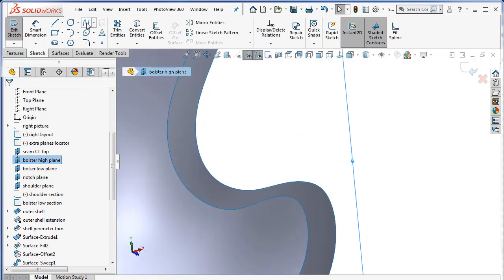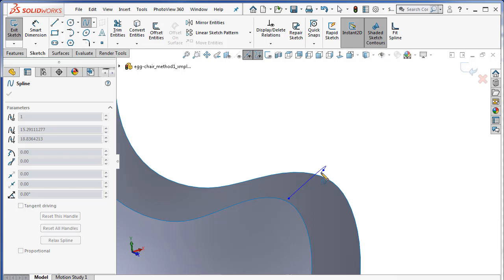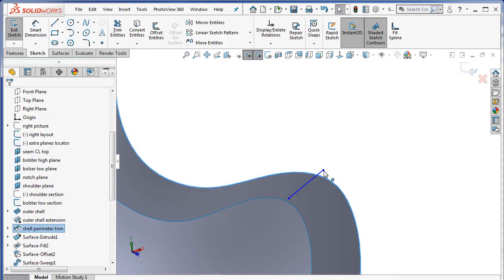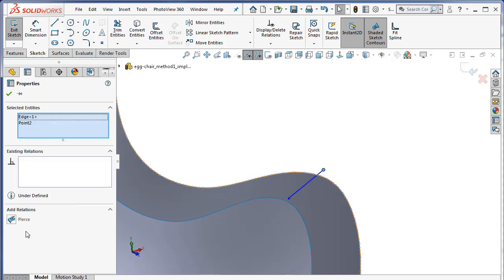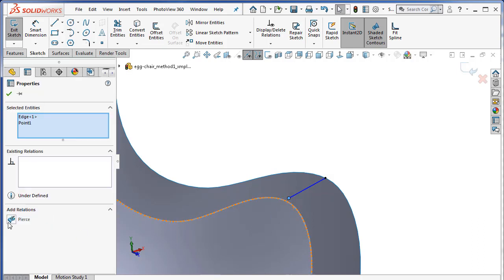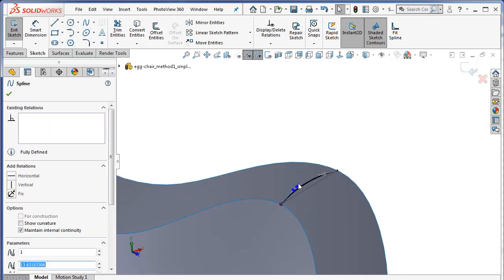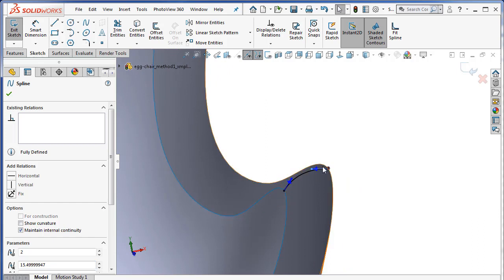and I'm going to draw a spline from this line to this outer edge. So just drag this out here, a 2-point spline, and I'll pierce to either edge here, or both edges. Pierce to the outer, pierce to the inner edge, and then I want to give this some shaping here. So I'm going to grab my spline handles and sort of shape this. That looks like that's going to be kind of a nice looking shape to give the impression of this cushion.